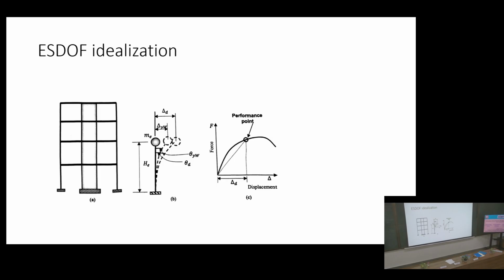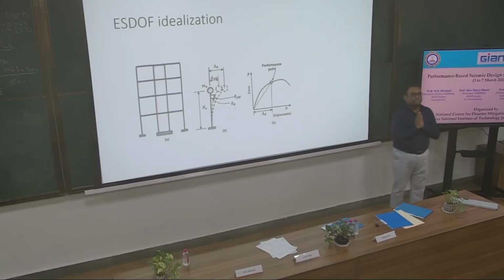Now, who can tell me what a plastic hinge is? I think you're on the right track, but can you be louder? When the moment reaches the plastic moment, a mechanism develops and plastic hinges start to form. Okay, what does a plastic hinge do? Can it carry moment?